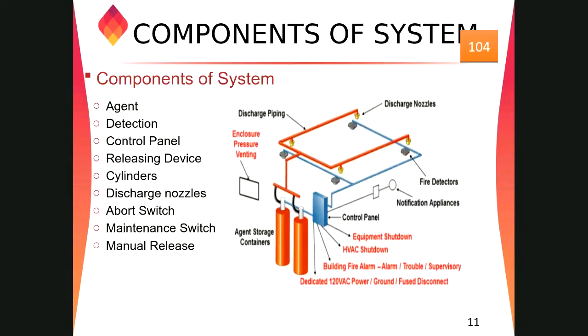Yeah, I remember witnessing a couple of years ago a CO2 system full discharge test. And as you just mentioned, the quantity of CO2 usually needs to be a high concentration inside the room, around 34%.